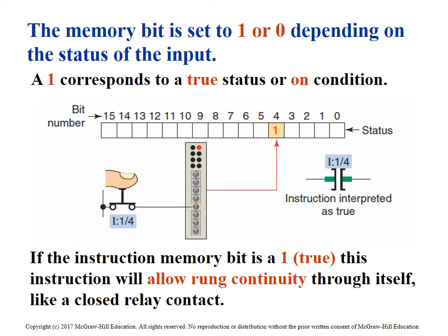The memory bit is set to 1 or 0 depending on the status of the input. So if it's normally closed, it'd be set to 0. If it's normally open, it'll be set to 1. So that's what they're stating here.